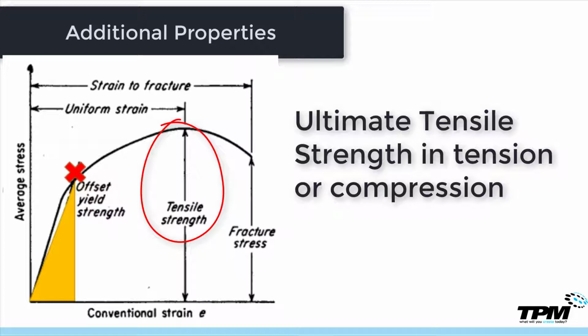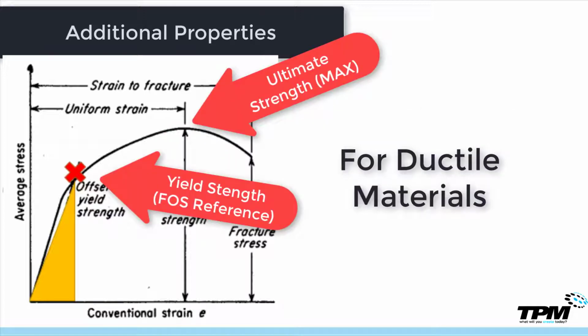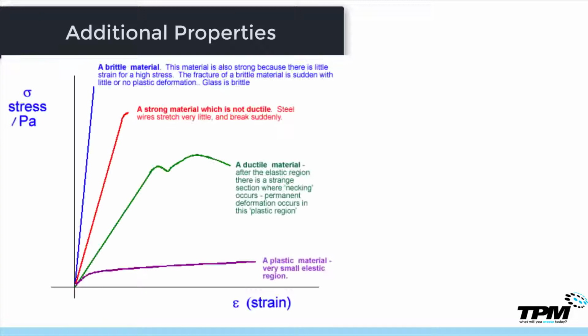This is a number which is useful to have when defining when a part has fractured in loading, as some parts are designed to fail to protect other parts. The ultimate strength and yield strength are typically different on ductile materials, but brittle materials usually do not yield noticeably and fail at their ultimate strength. Many manufacturers list the material tensile strength and compressive strength as their material's ultimate strength in specific types of loading because that is how the samples were tested in a laboratory. These numbers are not required, but it is recommended to obtain them.